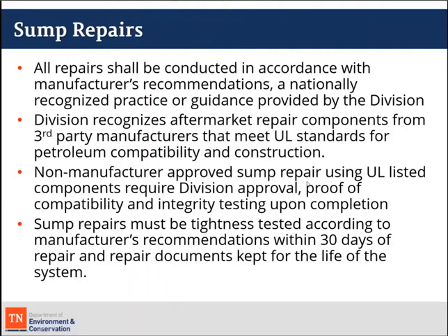Any sump repairs must be tightness tested. Again, this is the same as integrity tested: hydrostatic test, vacuum test, whatever your test procedure may be, according to the manufacturer's recommendations, within 30 days of the repair.